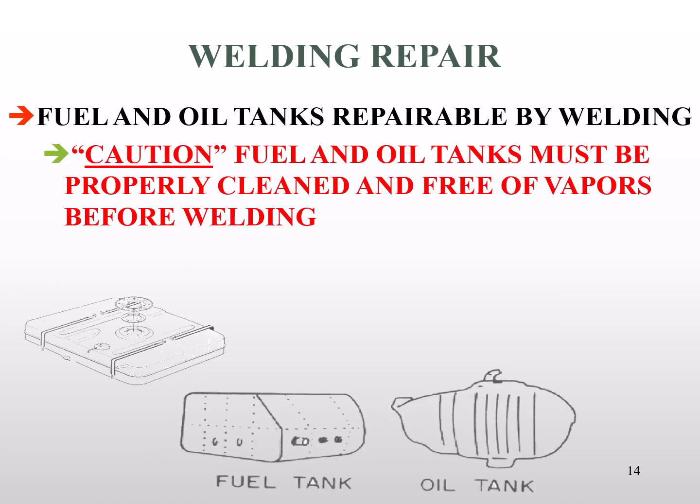Many fuel and oil tanks are repairable by welding. However, it is a very dangerous undertaking to repair a tank, especially something that's held a volatile liquid, because there is the potential that it can explode. So in order to weld these, you must be trained in how to purge them and make sure that they're continuously free of vapors before you would ever attempt any type of welding method. Many people have died in this process because what they were welding on contained some form of a flammable gas, even though they thought they were clear.